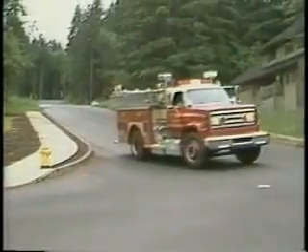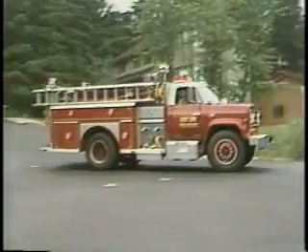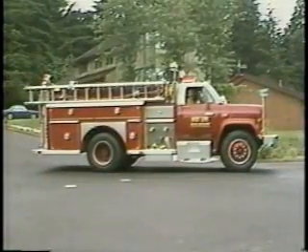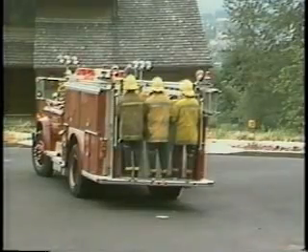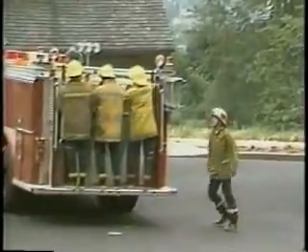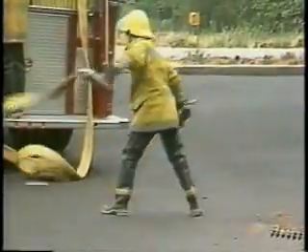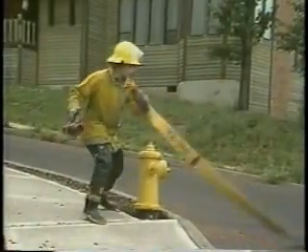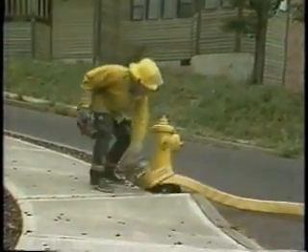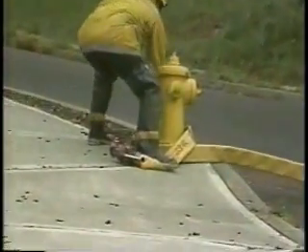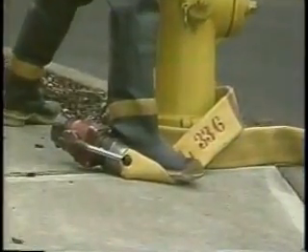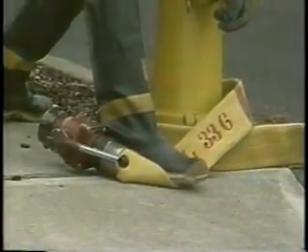Taking a hydrant on the run does not save time and may result in injury to the hydrant operator. After the apparatus has come to a complete stop, the hose bed finish is pulled from the hose bed, along with the tools and equipment necessary to complete the hydrant connection. A loop is thrown around the hydrant with a foot planted on the end of the hose to anchor the supply hose to the hydrant.